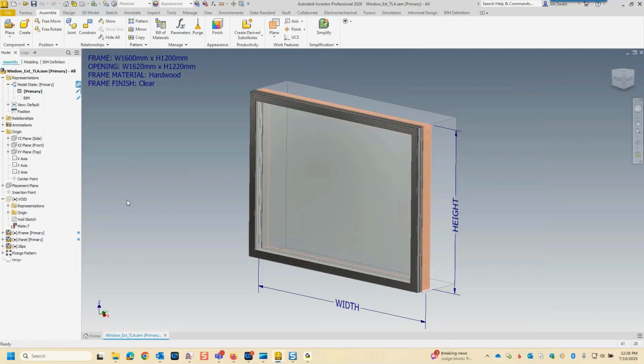I will say, though, that this needs to be a self-contained assembly, meaning it's going to have its own project file that's going to look at the folder where this is. Anything this assembly needs to be directly either in that same folder or down in the subfolder underneath. Think of it as just being the tip of the iceberg, and everything needs to be in the same iceberg. You can't be referencing other icebergs for parts.